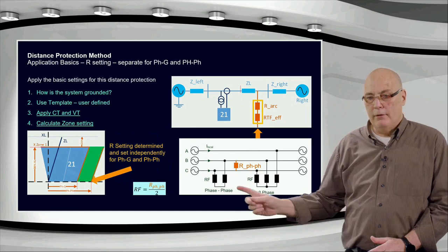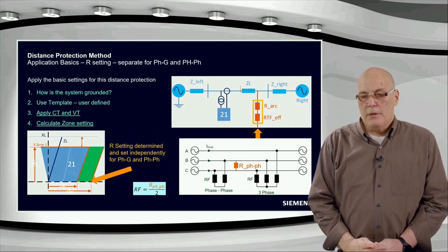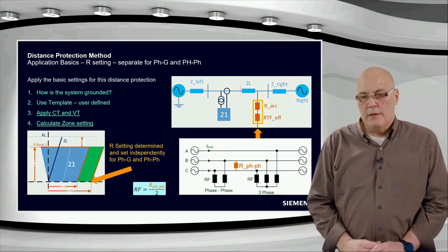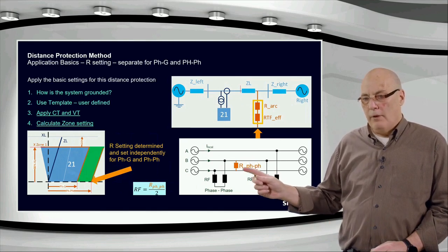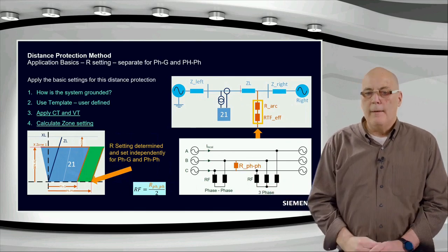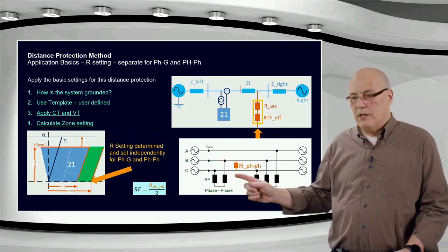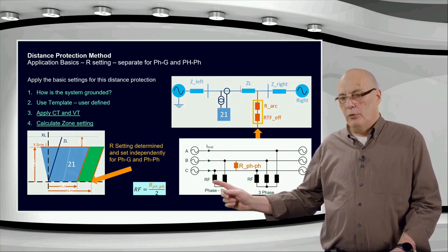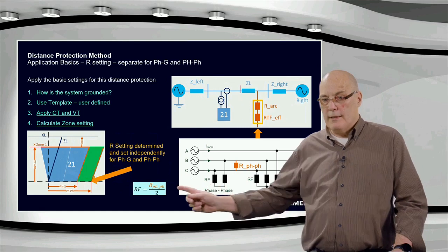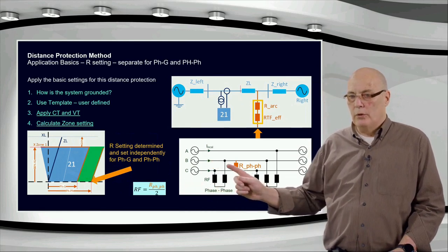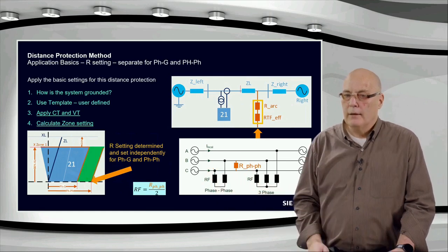And here I made a very interesting diagram, and you must be very, very careful, okay? Because if you're going to draw a fault resistance, you must decide, am I going to draw it like this? Here you can see the example for the phase to phase. And this is the common way of doing this in that technique. But remember, the phase-to-phase loop is going to measure the impedance only in ZL. So this is split into two. That's why I actually prefer to draw the fault resistance like this. And you can see this RF, if you draw it like this, is effectively the phase-to-phase resistance divided by 2. Okay, but you go around the loop around here. Compared to orange, compared to that technique, it's a factor 2.